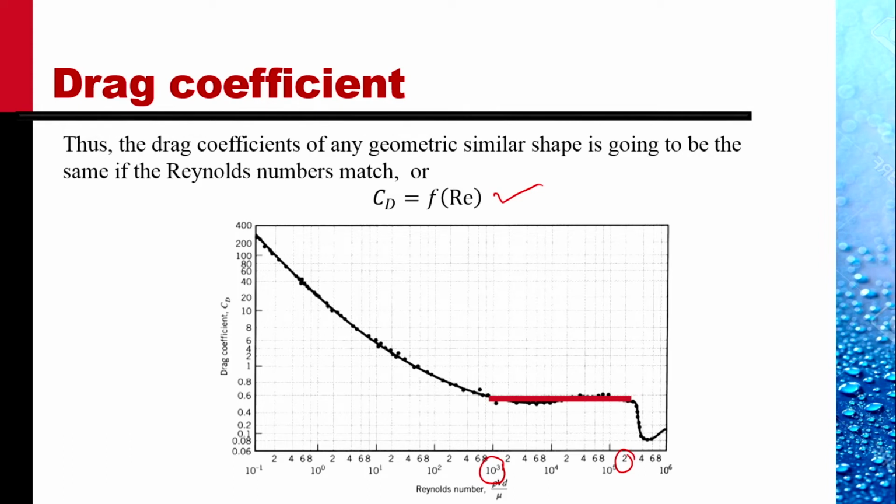not mentioned. The drag coefficient for a sphere in laminar flow is given as about 0.6, for a flat disk about 1.1, and so on. Reynolds number is not mentioned because for most engineering applications, the relevant range of Reynolds number is this. So for this automobile that we had, we didn't need to match the Reynolds number.